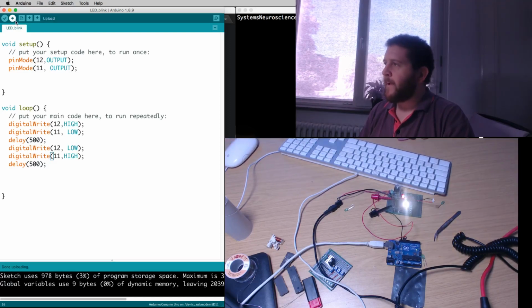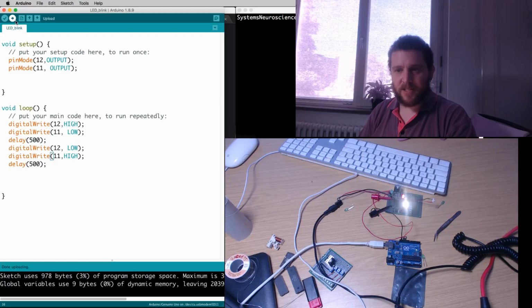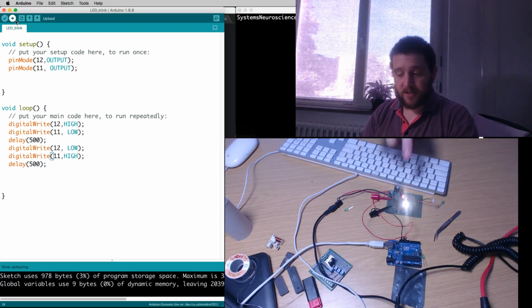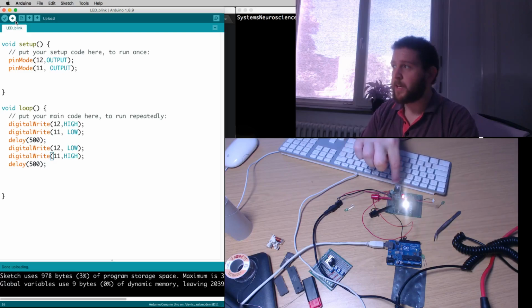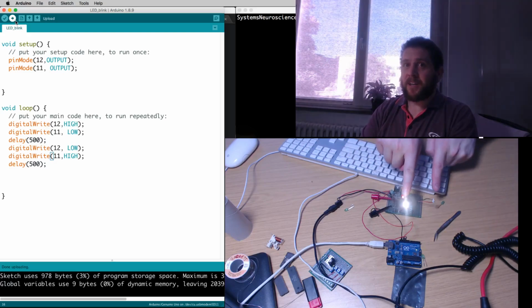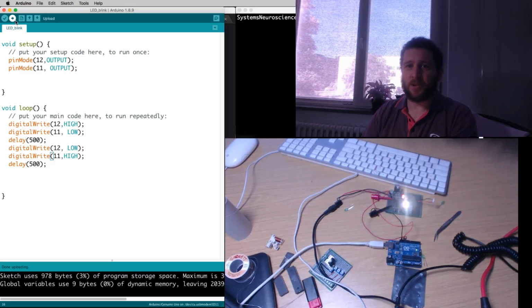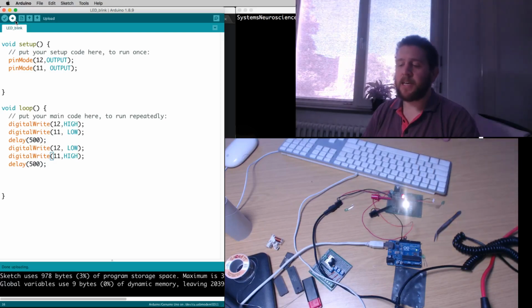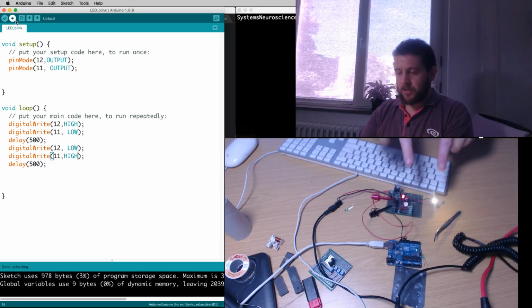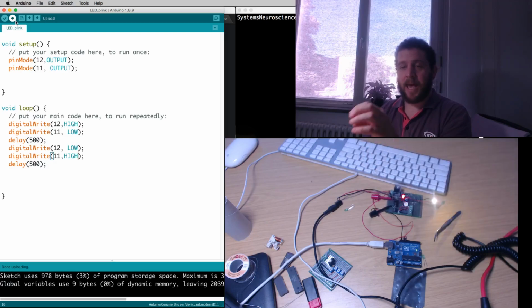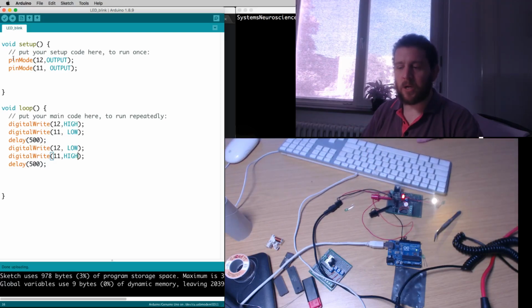All right. So this is a slightly more advanced output where we've used a transistor switch, we've used a regulated voltage power supply here. We have to be aware that the Arduino cannot drive too much current. We need to use something in between the Arduino and our output LEDs. In this case, it's going to be a transistor switch and the regulated voltage power supply coming out. So from now on, I will use this circuit, this electronic component, and we will now think about how we talk along the serial port to Python. We'll leave this video here, and I'll see you in the next video.